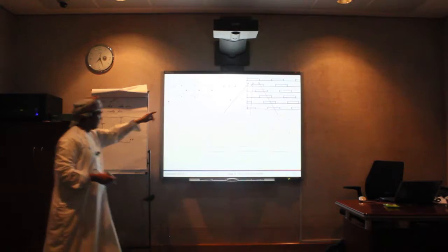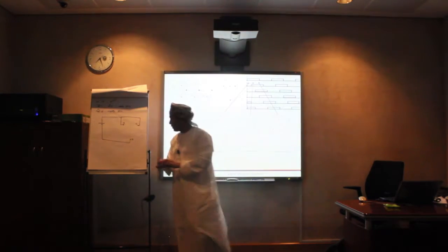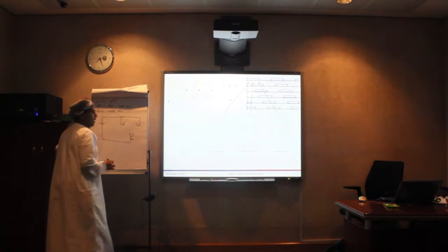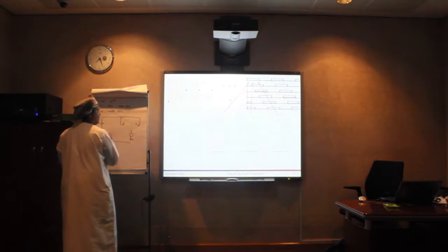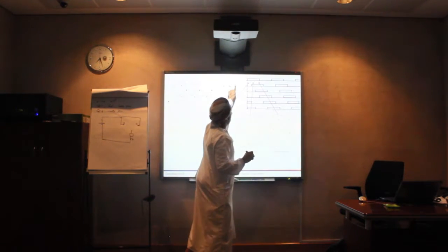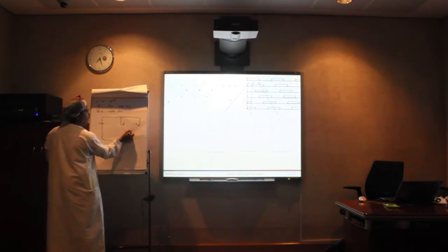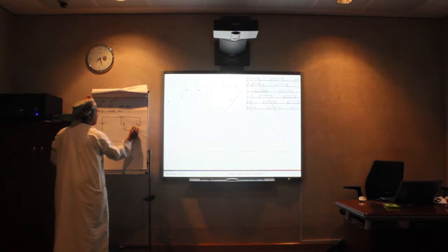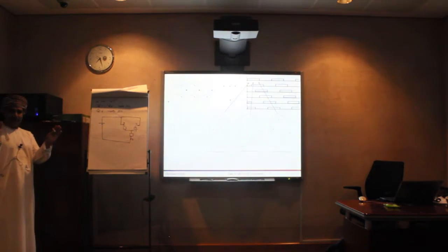Now, this is the three-phase load, right? B is connected to this point, okay, this is point B. So there is a load, or resistance, here. I'm assuming now all of them are balanced. And then the neutral is in the middle, which is this point. Now, from this point, one load goes to C and one load goes to A, right? So from the neutral, one goes to A and one goes to C. This is how it looks from the circuit analysis.